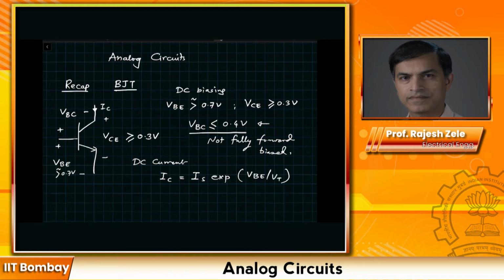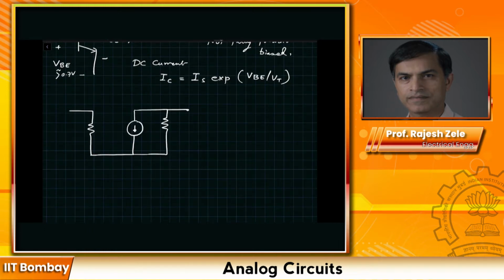In this mode, the small signal model of the bipolar junction transistor, please draw it yourself. Between base and emitter, we have R pi, and here is our small signal VBE voltage. From collector to emitter, we have the current flowing, which is GM times the small signal VBE voltage. And then from collector to emitter, there is Rout, the output resistance of the device.